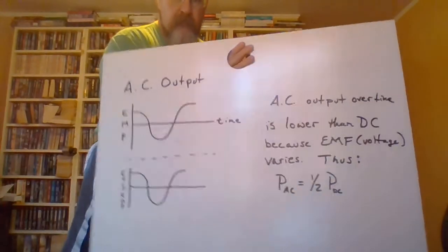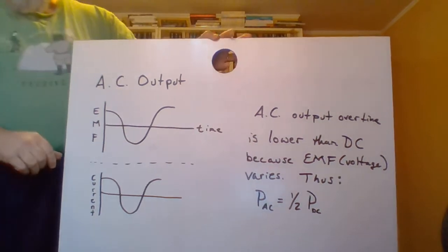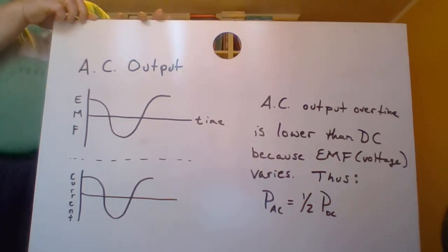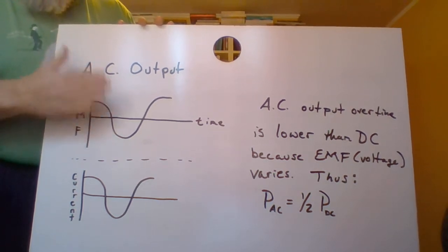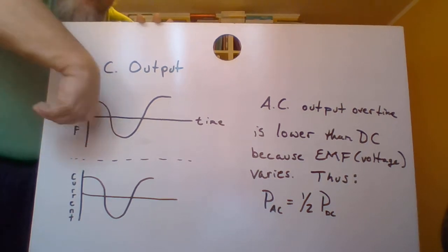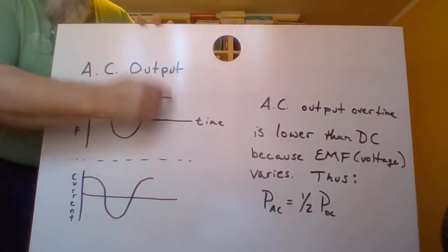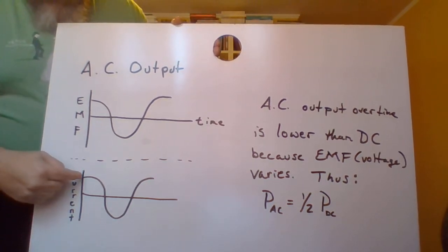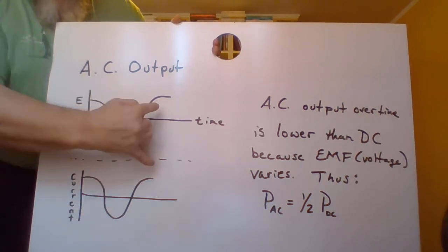And the reason they did this was because, well, if we have it connected through slip rings and we get this alternating current, this is the sort of output that you get. Okay? This is your AC output from a generator that has its armature directly connected to the outside through slip rings. All right? Your EMF is going to start at a maximum when you have the maximum face, and it's going to decrease once it rotates 90 degrees, and then it's going to start going in the other direction as that face flips around, then it goes back up. And then you just keep rotating and go through, and this will go on forever. And the same thing happens with the current. When it's connected out, the current will also vary with the voltage, okay?